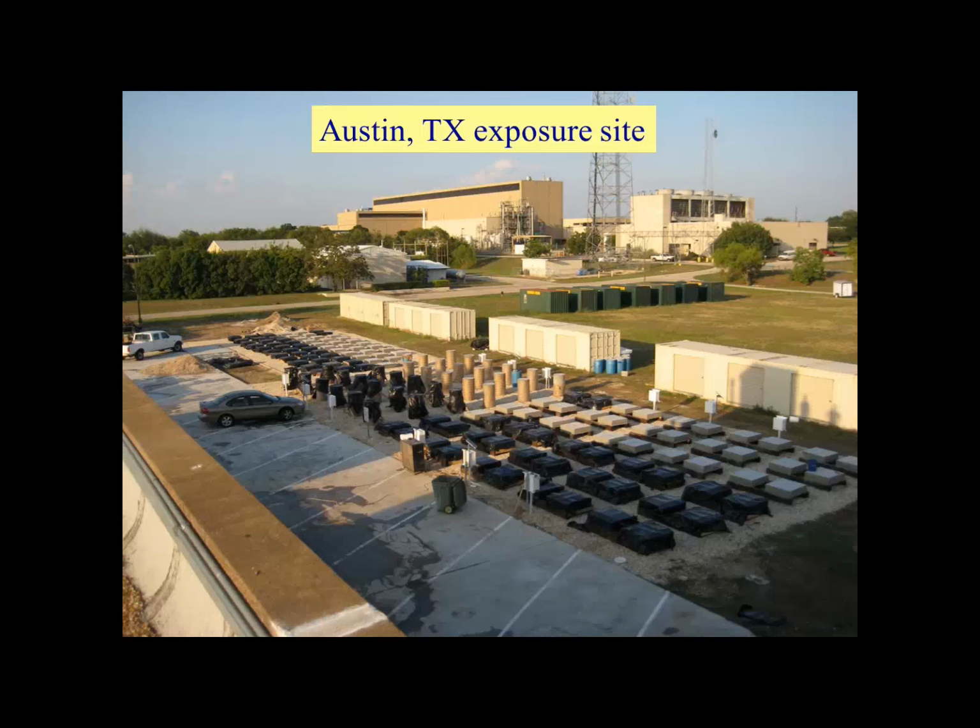So our group and many researchers have worked with lithium as an admixture, and it's very effective if you put enough lithium into concrete, and it can provide long-term resistance to ASR-induced expansion and cracking. So the best case for using lithium is to use it as an admixture. Just make sure that you put enough in for that given aggregate type. Generally, that requires laboratory testing to determine how much is needed. But the data from our exposure site, as well as sites in Canada and the UK, show that lithium is a long-term solution for ASR when enough lithium is put in.